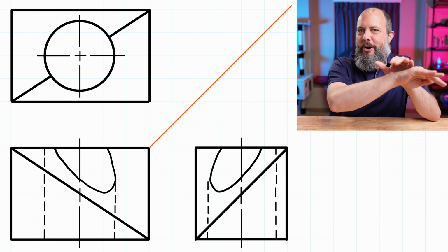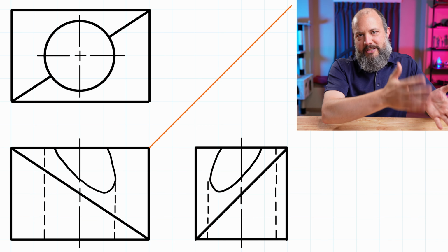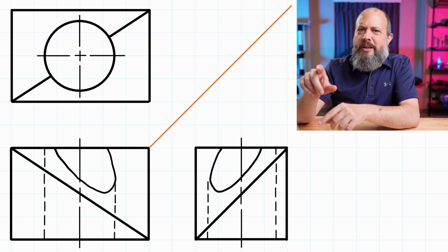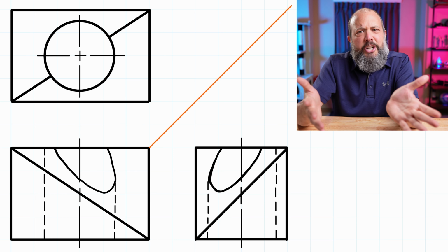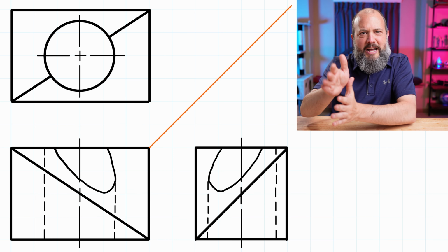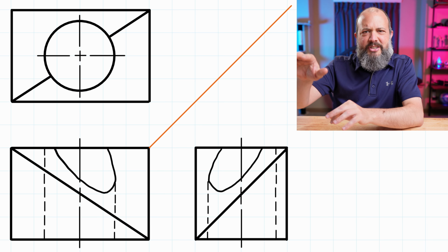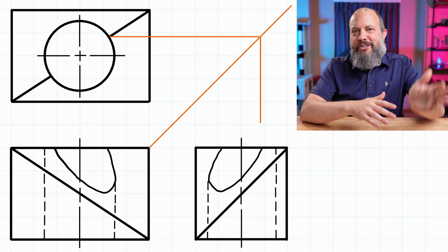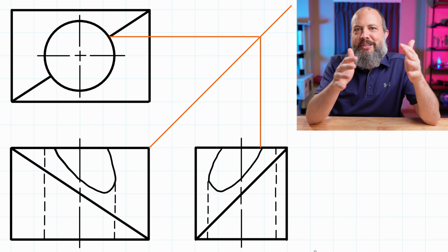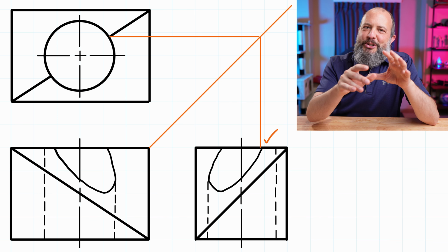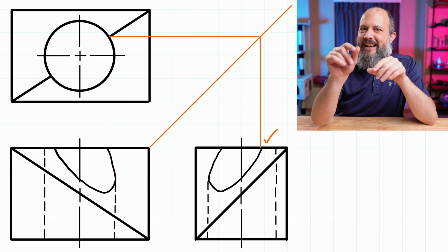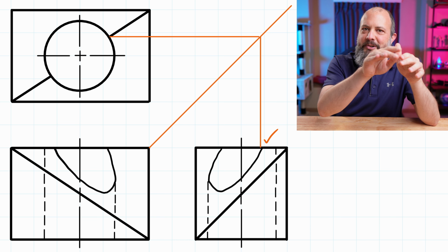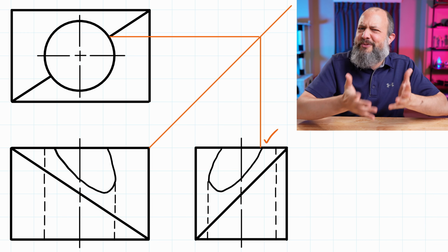It intersects where the diagonal oblique surface reaches the top. And then the short little stubby missing line, it also doesn't intersect the drawing, but that's just because my drawing's bad. The curved arc should intersect my missing line. I think my hidden line looks good, so I'm actually going to just redraw the arc a little bit to be at the right place. Yeah, and again, I'm tracing this orange line straight up and then straight over across the miter line to the top view, so you can see that where this weird arc on the right view reaches the top, again, it doesn't correspond to the quadrant. It corresponds to the part of the circle that intersects the top edge of the oblique surface.